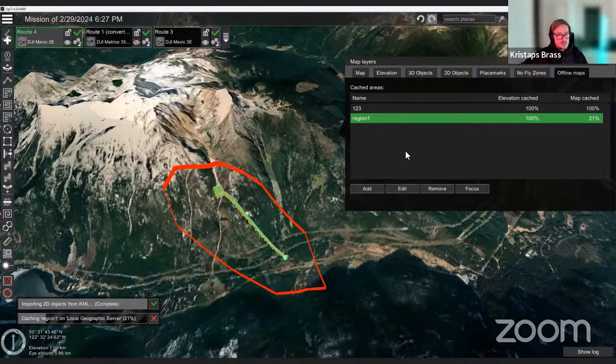If you're in the field and you need to connect your drone to GCS, you can simply use any kind of network router or mobile phone hotspot. Again, it doesn't need to have internet, it just needs to be able to connect both devices. In fact, you can also just use USB tethering between the remote controller and the computer to connect when you need to. Or just cache the routes within the DJI mobile controller and then fly without even having to open up your computer.